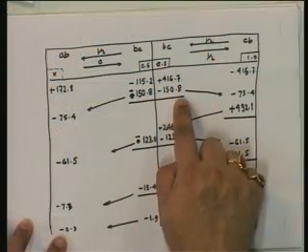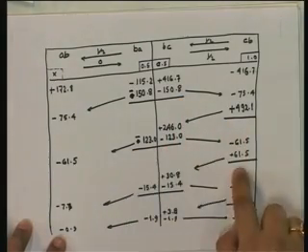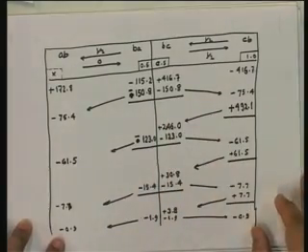In this particular case, we are distributing B, then we are going to distribute C, then we are again going to be distributing B, C, B, C, B, C. This is the physical procedure. We will see in the next lecture that this becomes a very cumbersome procedure. Ultimately what we have to do is look at all the joints, look at all the unbalanced moments, distribute them, then carry over, then continue.